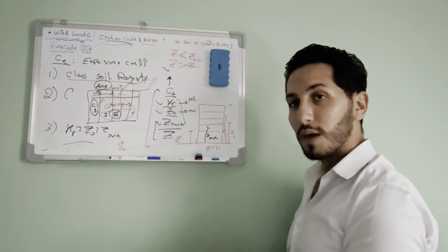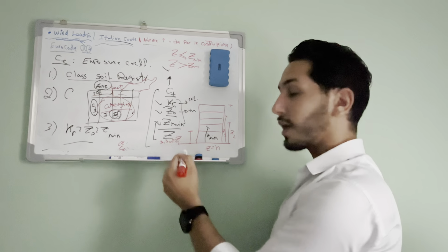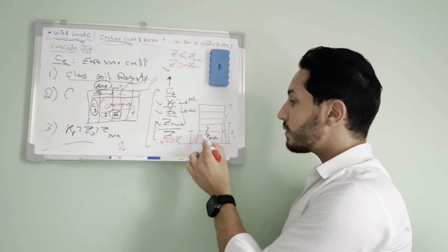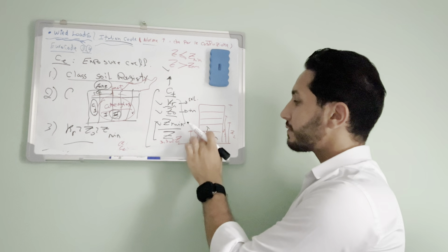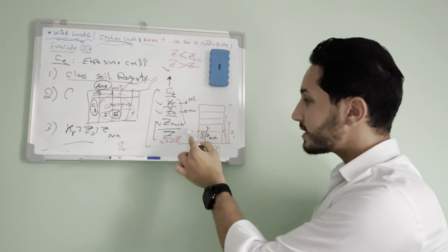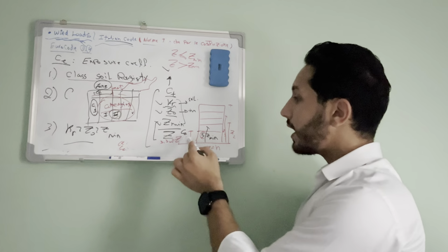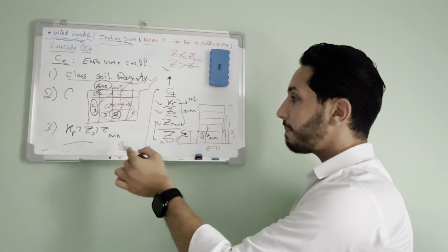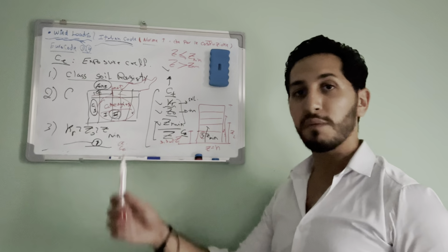Let's assume a quick example here, that this Z is equal to 3.3 meters, okay? And the Z minimum is equal to 8 or 5. Let's just say it's 5. What's gonna happen here? For the first floor, by the equations given to you, you get that the CE is equal to this equation. Just replace the Z value by the Z minimum value.